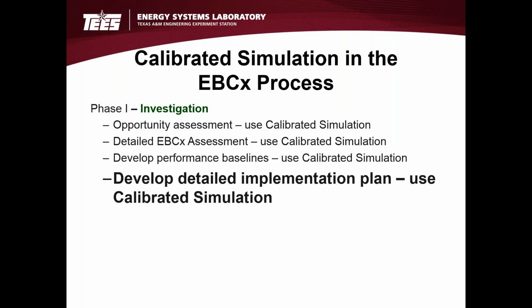The commissioning process is one where, once the on-site assessment has been done and the decision has been made to go forward, typically the engineers will spend substantial time taking measurements at individual terminal boxes, things like that, before they develop the actual measures that they will recommend for implementation, which will then be reviewed with the site staff and approval obtained before they're implemented.